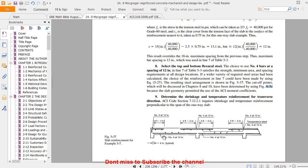Because the panel spans are the same, we are allowed to use L by 3 and L by 4 coefficients. But if they are not the same, let's say this is 15 and this is 20 feet, then we are not able to use those L by 3 and L by 4. We have to calculate the theoretical cutoff points and the actual cutoff points. So this is the whole procedure till now.